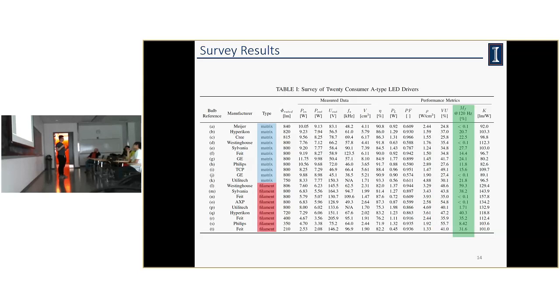You're going to have a bigger converter, so that means there's more room to try to handle flicker, because flicker basically has to do with how big your electrolytic capacitor is. The more volume you can spare, the bigger that cap can be. The filament, that space doesn't exist. If you saw what I handed around, it's a very tiny electrolytic. I'm pretty sure some of the flickers are handled very well. So, I don't know, take it for what you will.